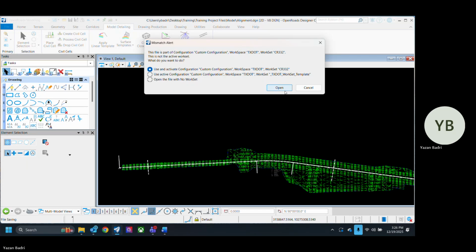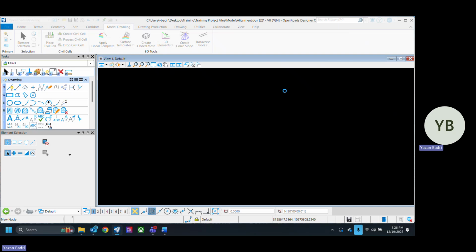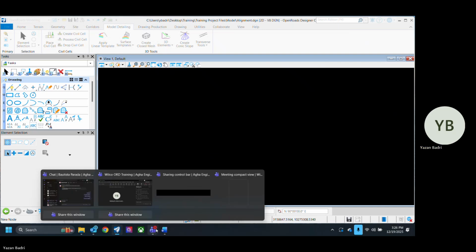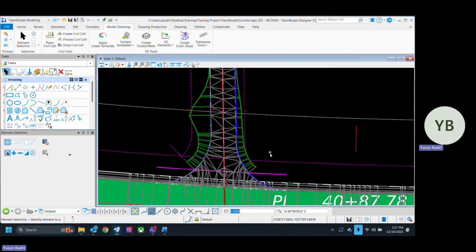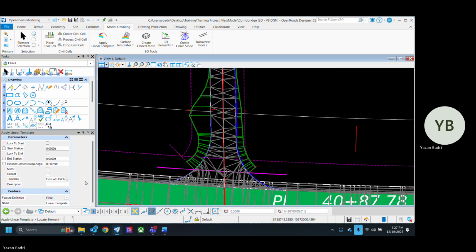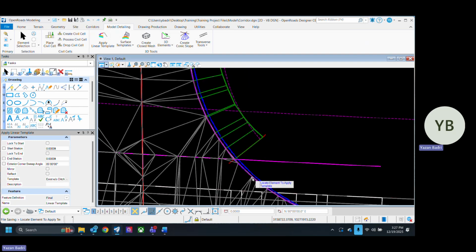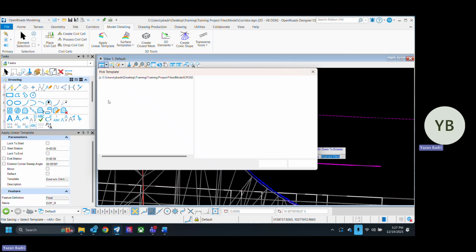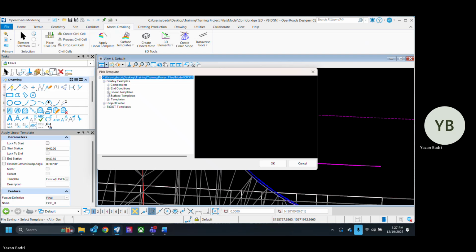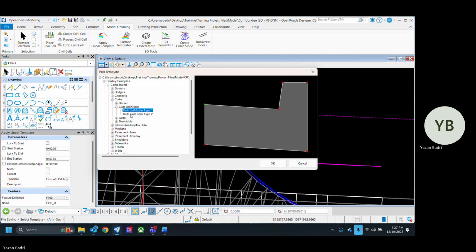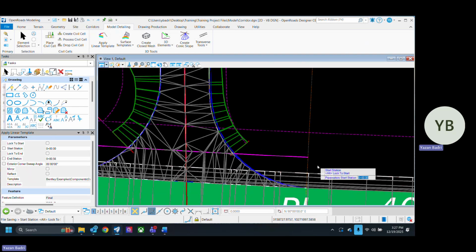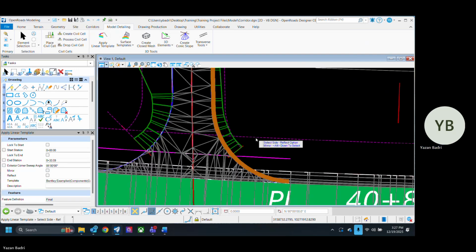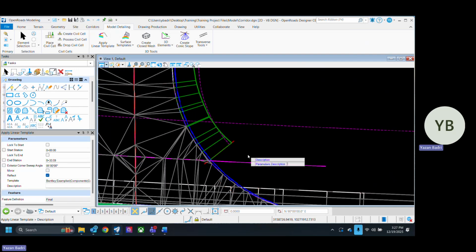Corridor. Say I want to add a curve to this driveway. Go to linear. I choose the element, apply template. So just choose this element. Now I choose the template that I want to apply. You can imagine this could be used for a barrier or something like that. For example, curb, mountable curb, sure. Concrete curb. So I want to start from here, end it here. Do it on this side, no description.